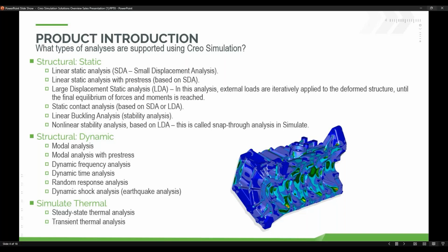Within the thermal analysis, we can do conduction, convection, and then the third type of thermal analysis is radiation. Radiation, we kind of have to simulate, no pun intended, to get to it because we don't do true radiation simulation. Radiation simulation is the transfer of the heat via electromagnetic waves. Conduction is, as you would suspect, two pieces touching one another and the heat being conducted from one to the other, i.e. the stove touching the bottom of a pan.